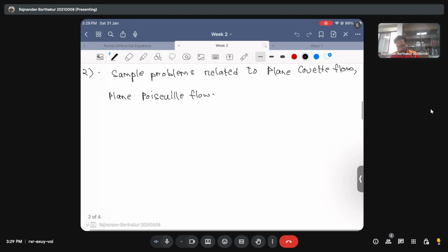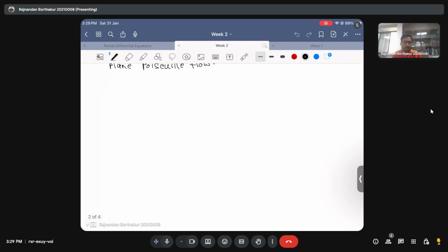So what we saw, using the Reynolds transport theorem for momentum, is that the ultimate equation we got is the much celebrated Navier-Stokes equation. I'll call it NS throughout this course. When written in vector form, it took the following form: rho times the material derivative of velocity, capital Dv/Dt, is equal to minus the gradient of the pressure, plus viscosity times del square of velocity, plus rho times the body force.